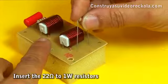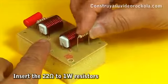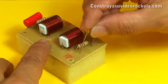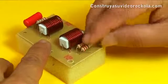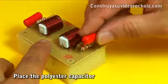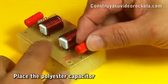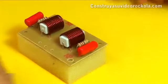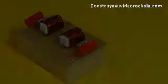We place the other 2 resistors of 22 ohms, 1 watt. And finally, we place the 0.1 microfarad capacitor. Remember to use as a guide the component mask, delivered in the PDF file.